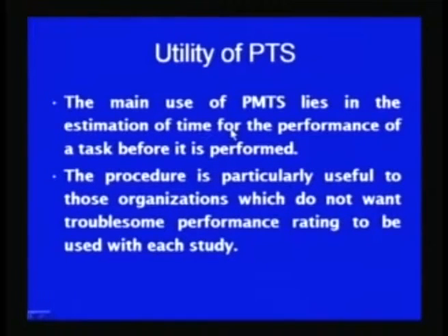Here in this method, the method which is to be followed for producing a particular component is broken down in the data sheet or record sheet in terms of the basic human motions required for performing the job, and then time values for those basic human motions are obtained from the predetermined time values in the data bank.